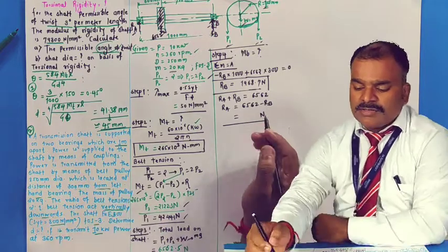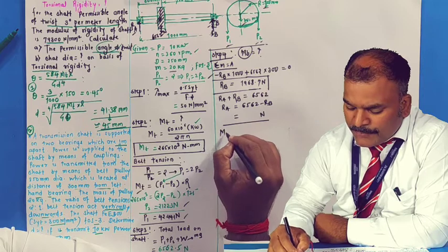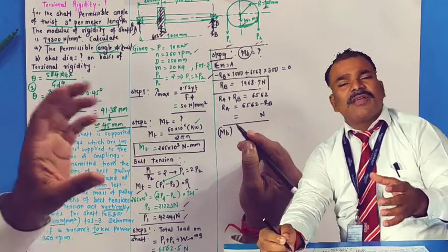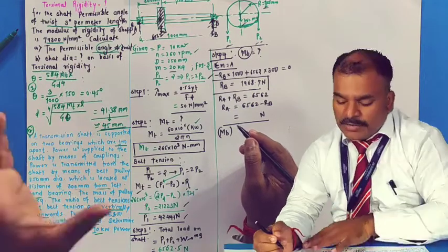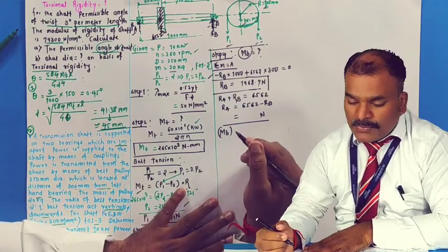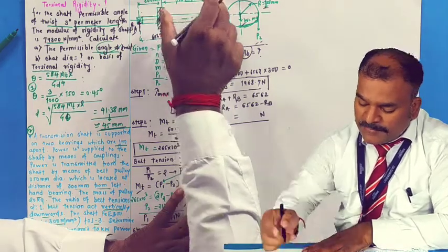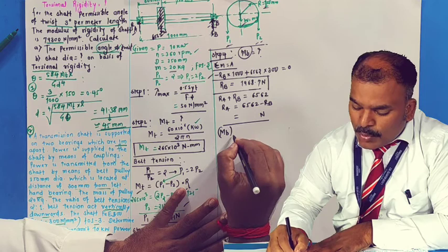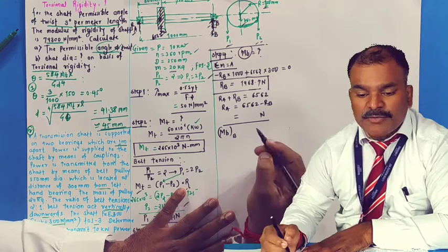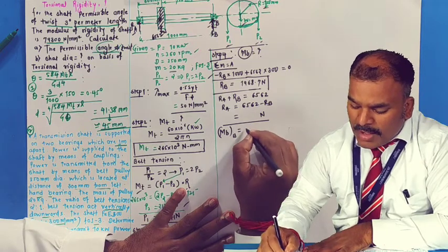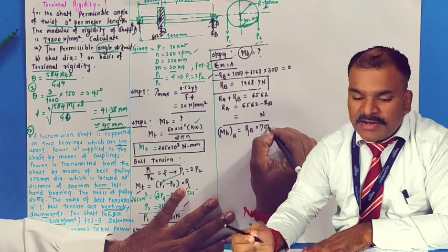Now our step is, we have reached up to bending moment. So we have to calculate the bending moment. Earlier it was very simple, but right now two bearings are there, and with respect to that we need to calculate. So I will have to say bending moment on the longest side, 700. So bending moment at point B, very important. If it is A, I will have to write accordingly. So that will be RB force into perpendicular distance 700.